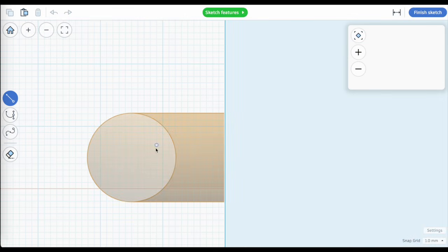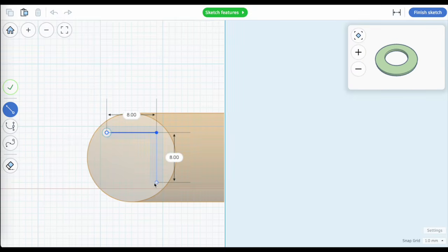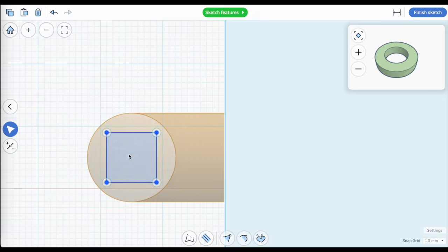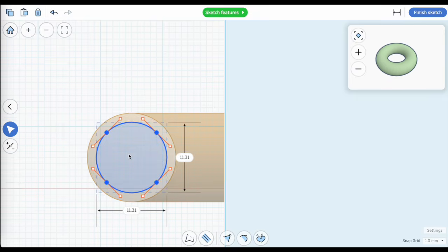Now that's important because when I open this up, I want to ensure that whatever I am revolving around my center axis, this center axis is in line with the other center axis of this shape I see in the background. Because what I'm going to do here is create a slightly smaller circle that I will then convert and make into another tube, like so.